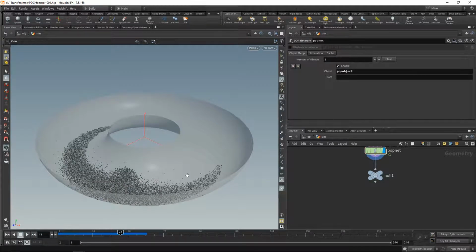So what I want to do now is select the outer area of this particle fluid, just the outer borders, and that's where I want to emit my foamy, bubbly particles, so that the foam emerges at the edges, at the borders of this fluid, and not in the center, because that would need too many iterations to push out all those spheres to the outside of my simulation. And for that, I want to only regard particles which have hit the collision geometry.